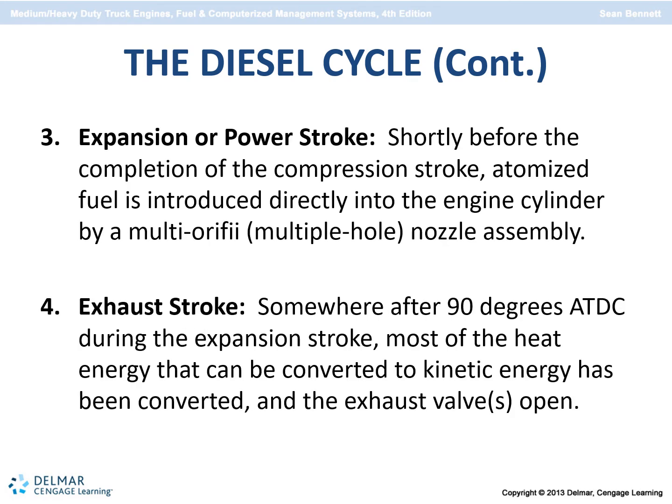The expansion or power stroke: shortly before the completion of the compression stroke, atomized fuel is injected into the cylinder, creating the combustion. That pushes the piston down, the power stroke. The exhaust stroke is the piston coming up with the exhaust valve open, forcing the burnt hot air out of the cylinder.